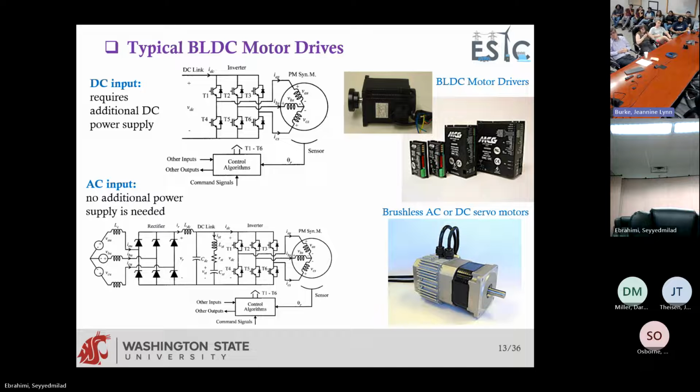So then what if you want to control the speed over a wide range? You need to have a power supply that allows you to control the frequency over a wide range, right? From very low speed to start up and then slowly increase it. That's why we need a power electronic converter. Basically, what it produces here is a set of voltages whose frequency you can adjust. To do that, you need knowledge of the speed of the machine, right? And also the position of the rotor.